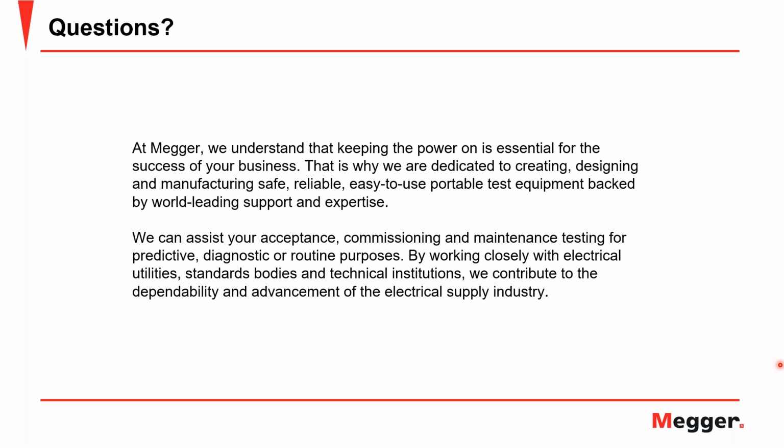Yeah, you're absolutely right, and that is one of the reasons why one of the first things that were implemented in microprocessor relays was the positive sequence and the negative sequence directional elements. Because obviously when you have a three-phase fault, all your polarizing signals could go down to zero, to levels that are not reliable.